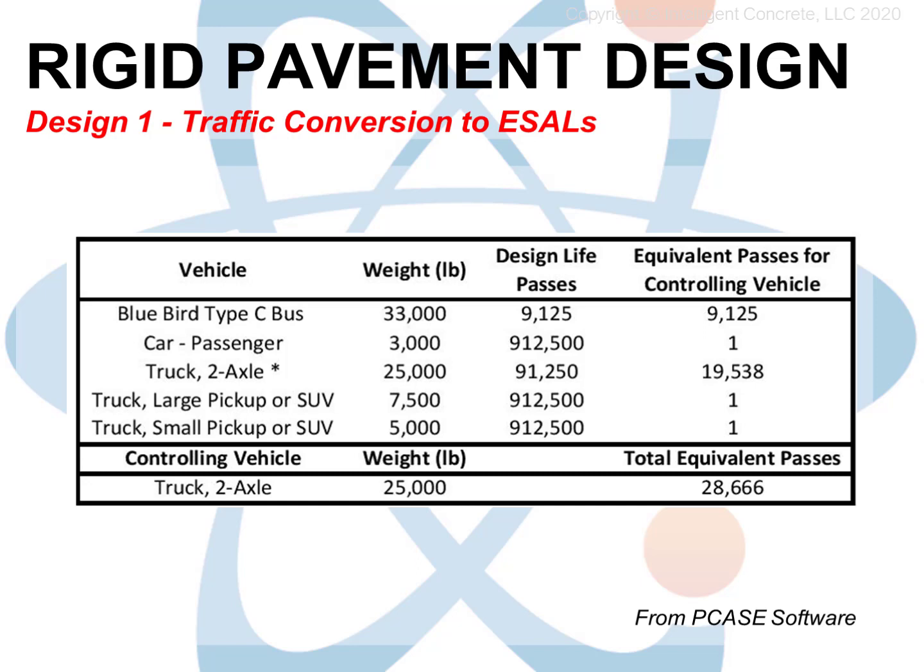This term is a mathematical construct that resolves the various vehicles into an equivalent single-axle 18,000-pound load. Clearly, very few vehicles will have any axle with an exact 18,000-pound weight per axle. It might be more, it might be less, it might be with 4 tires or 2, but probably not exactly the same. However, scientists and engineers have figured out a way to convert the weight of a vehicle, maybe with 2 or 3 or more axles of whatever weight and tire configuration, into what it would take to be equal